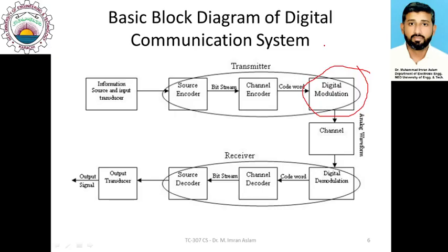Those pulses are also a form of modulation, because we use specific waveform pulses to represent the digital information. This type of modulation is sometimes called baseband digital modulation, or sometimes pulse modulation.